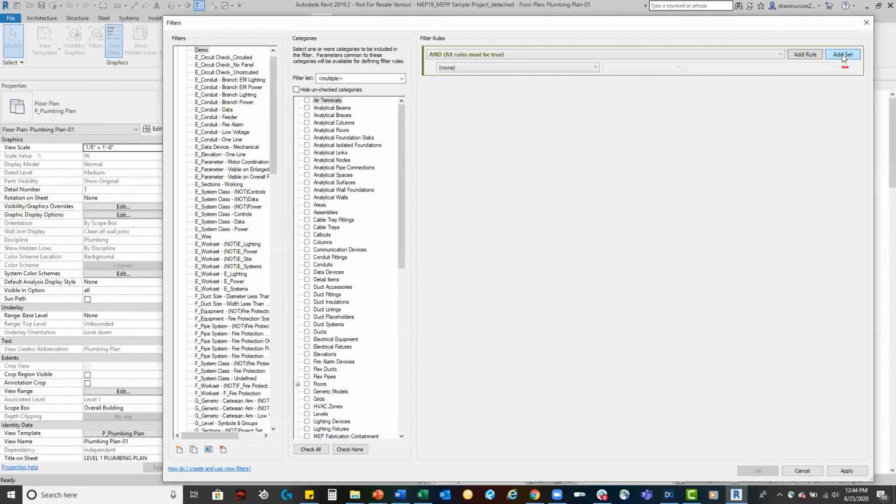One of the things that I have recommended to other clients as well is that if you do have to demo, say like half a pipe, for example, you make what we commonly refer to up north here as hockey puck connectors, because we all know if we set something to be demoed, that it strips its system data, strips all the data that we want from it. By making a simple hockey puck connector fitting, and it doesn't have to be anything graphical, guys,